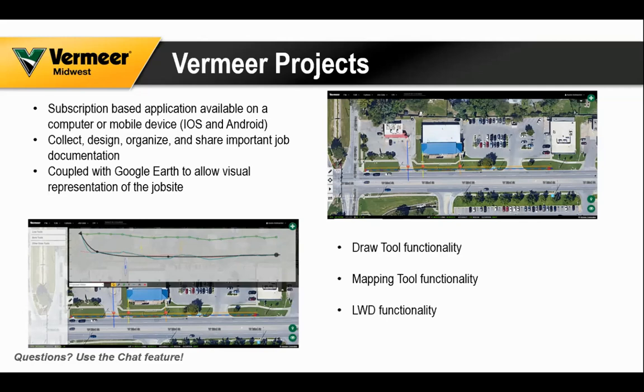The imagery on this application is actually provided through Google Earth instead of Esri. So Esri was just your imaging. This is pulling Google Earth data, so it's actually going to pull some topography data along with that satellite image. So again, on sites where you've got some construction going on, where you've got some things that have been changed around, it's not going to be terribly accurate, but it's going to be a nice starting point when designing a bore.